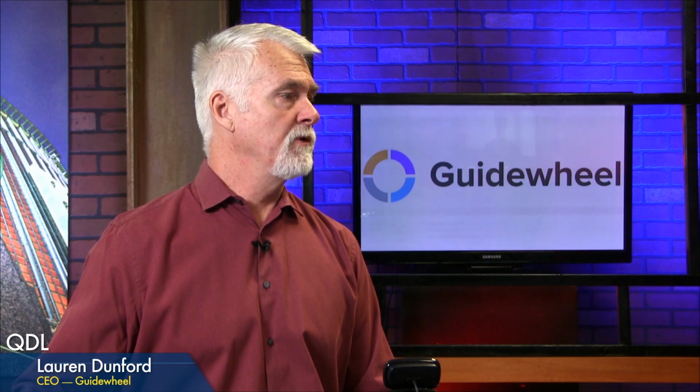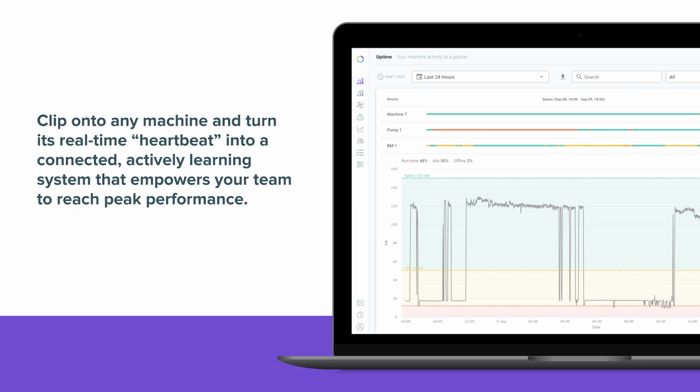I'm just going to pop that up real quick. Okay, so what I see, it looks like across the bottom is time of day, and the left axis looks like it's power, kilowatts. So this is basically showing me that the machine is on, then it's turned off for a little bit, then it's on, then it's off a little bit. Yeah, and you can also see where it's going red and yellow. Red is truly off, yellow is idling.